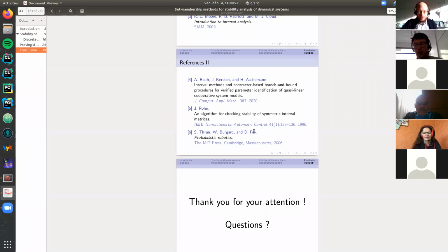Oh, yeah, exactly. The assumption of the constant was clearly made to simplify the problem, but we could definitely apply that method to a non-constant state. I think the easiest way would be just to define the tracking error. Yeah, absolutely. The goal is then the tracking error becoming equal to 0, and your extended state vector, I think it was called VK, would just be replaced by the evolution of the tracking error, where you have the steady state again in the origin. Exactly. Okay, thank you.